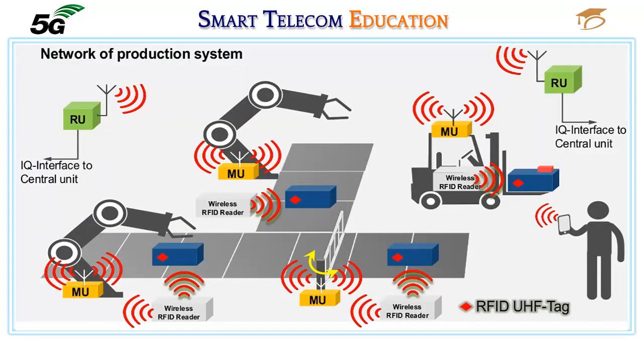Factory automation includes real-time control of machines and systems for quick production lines and limited human involvement. In these cases, the production lines might be numerous and contiguous. This is highly challenging in terms of latency and reliability. Therefore, the latency requirement for factory automation applications is between 0.25 milliseconds to 10 milliseconds with a very low packet loss rate.